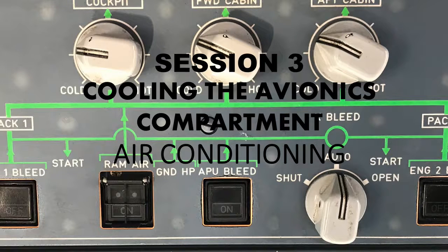All right, so let's start with the brains behind the ventilation system, and that would be the computer. The abbreviation is AEVC, which stands for Avionics Equipment Ventilation Computer, and that automatically controls the ventilation system, being able to manipulate the proper configuration depending on the conditions of the plane, in flight or on the ground. This is in relation also to the aircraft skin temperature. So those different variables are playing a part in what the computer is going to do and being able to control that cooling.